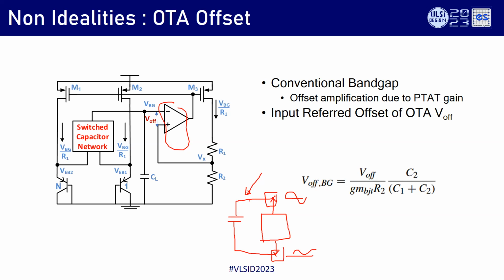PSRR. Whatever PSRR transfers from VDD to output, the VSS also should transfer exactly the same way. The way the noise transfers either from the power supply or VSS to the output is the same, but the magnitude is suppressed because of the low impedance nodes at the BJT.